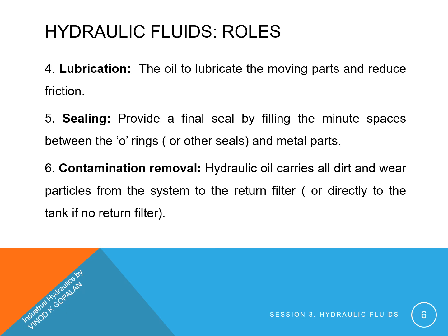Next, sealing. The hydraulic oil provides a final seal by filling the minute spaces between the O-rings and the metal parts. Sixth point is contamination removal. The hydraulic oil carries all dirt and wear particles from the system to the return filter or directly to the tank if there is no filter placed.